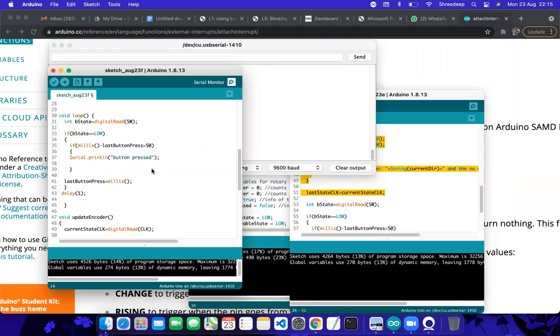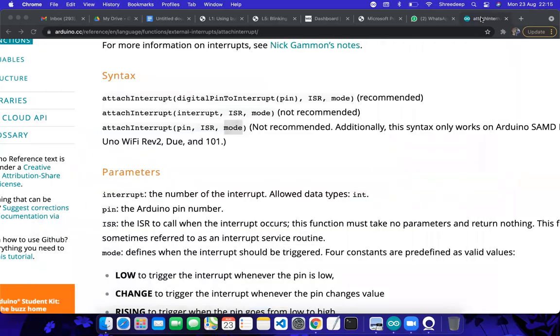So let's say you have 5 sensors and 4 actuators. Out of that, 2 are very crucial. If you miss one data from, let's say, the GPS sensor or the clock, RTC, or maybe some other device, you might lose a lot of other stuff as well. So you better connect these two as the interrupt. And we have another thing to cover before we call it a day today.